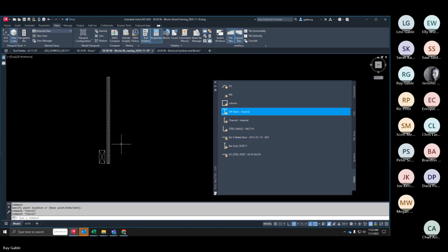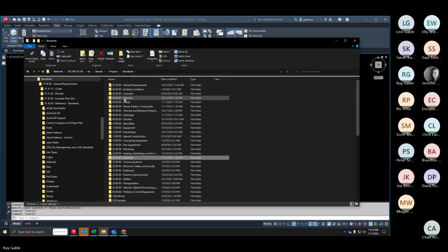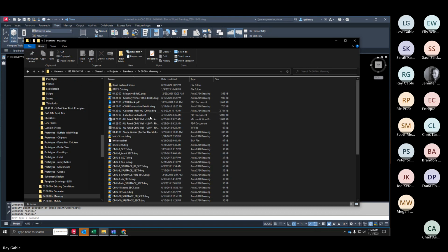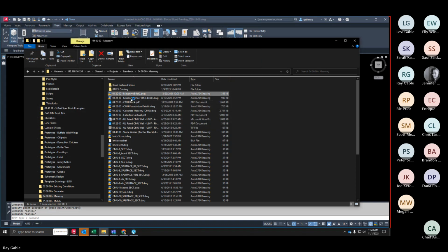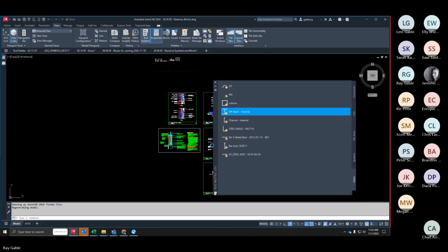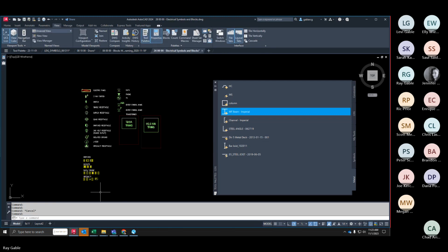Yeah, I do. Do we have a masonry one? I found some unique CMU dimensions. And if we could get maybe a brick and a standard CMU unit that, when we're doing something, everyone could array or do whatever it is in AutoCAD these days. Because I know that's what I used to do, is array those things up, and I had it set so I could offset that thing 3/8 and I could go up 10 feet and it coursed out.